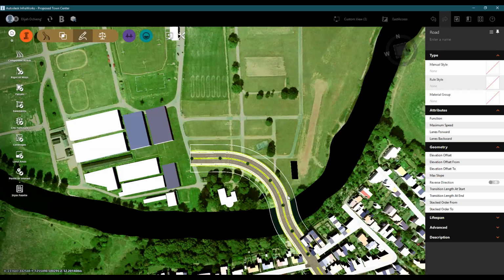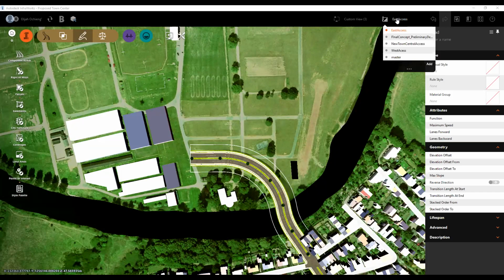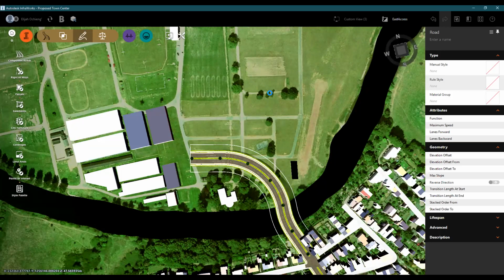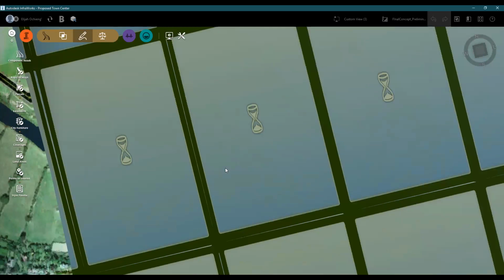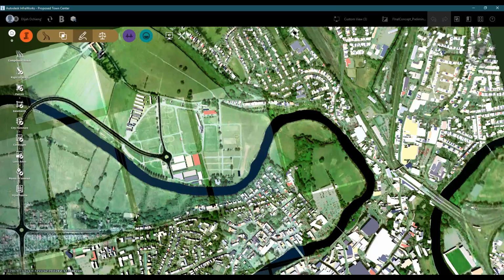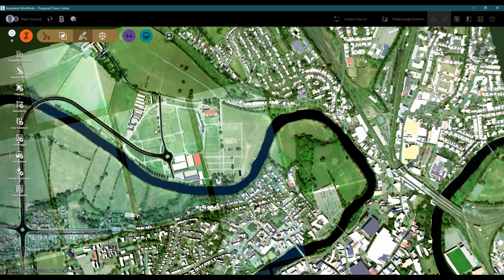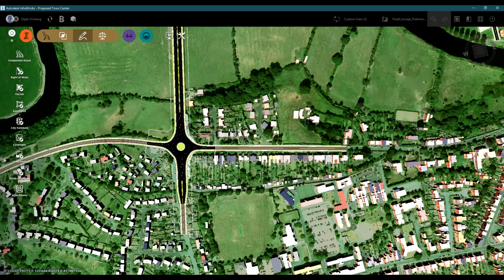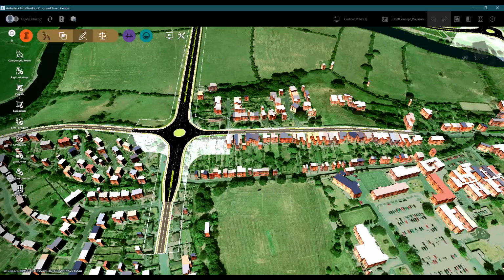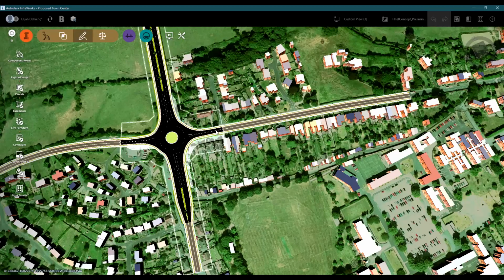Are there some conservation areas that will be affected by the project? My most feasible alternative, from the number of considerations I made, I found to be the one running on the western part. So I'm switching to that new design alternative. I developed a new alternative running from the western part, linking up the existing road on the roundabout here. Again, this was an existing roundabout. I was also able to establish for it a right of way, still 40 meters wide, showing how it's going to run.